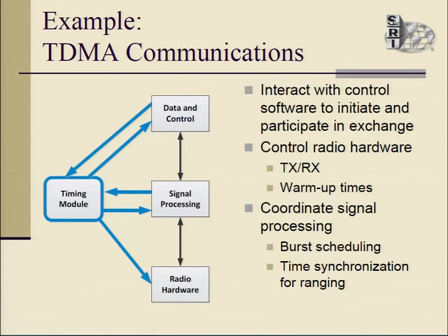Here's a little notional example of how we use the timing language to build this system. Again, this is just a piece of it, but the piece kind of coordinates the operation of everything else. There's a timing module, which also works with data command and control elements of the software, with signal processing software, and is also used to control the radio hardware in order to execute this protocol with precise timing, to warm it up in time so that it's ready to transmit when the opportunities come up, and to coordinate the signal processing, to schedule the bursts, and also to coordinate synchronization between devices.